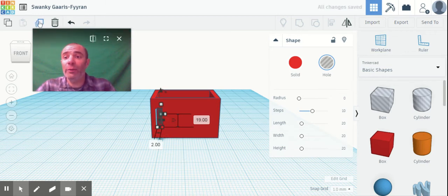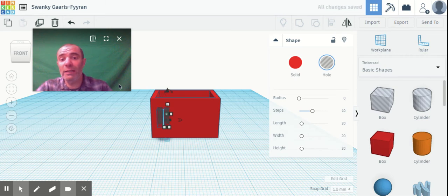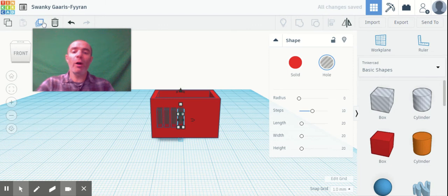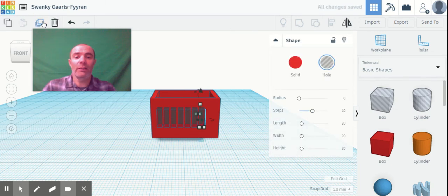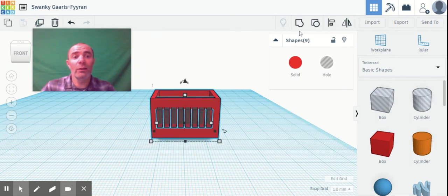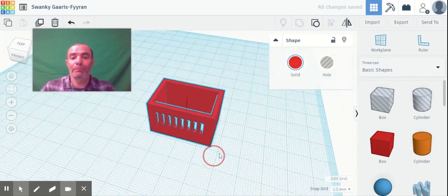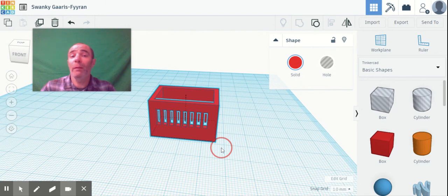It's selected. I duplicate it. Now I'm going to use my arrow keys. I don't click or do anything else. I make sure there's a space between it. And then I hit duplicate again. And it'll respond to what you told it to do. It's basically coded to continue making windows however many spaces across. Now I can left click this whole box, group it, and I have a pile of windows right there. Pretty neat. Have fun, play around with it, see what you can build.